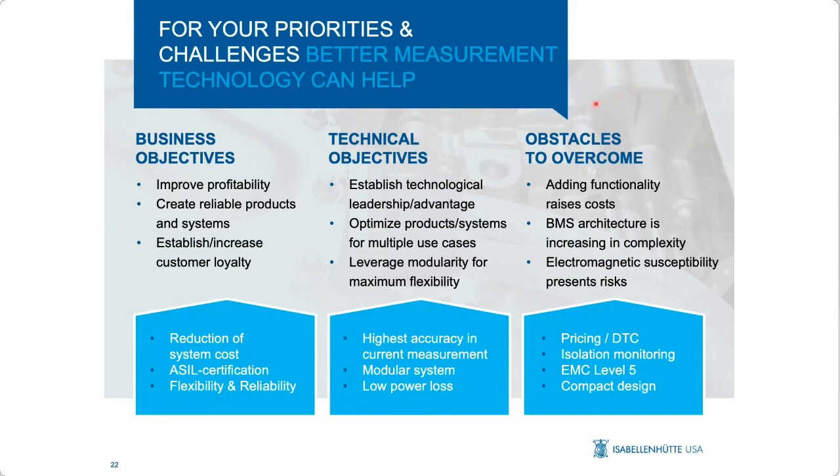Lastly, with regards to the obstacles that you want to overcome, adding functionality almost always raises cost, and as we learned, the BMS architecture is getting increasingly complex. So important items here are price reduction, a reliable isolation monitoring method to achieve high EMC levels with your smart sensor, and a compact design of the sensing module.